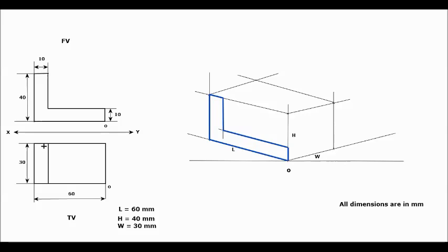Now if you observe the top view, this small rectangle is visible, and this small rectangle is for this vertical portion of your front view, or of your L plate. So here a complete rectangle is visible. So for completing that rectangle, first from this particular point, we'll draw a line parallel to the 30-degree inclined line, or parallel to your isometric line, and this is your actual rectangle which is visible in the top view. So we will make it dark.